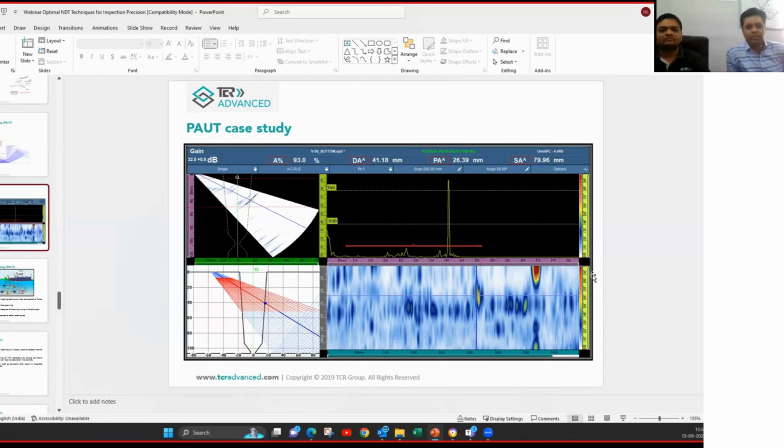Coming to your question about tank bottom plate inspection. Now there are techniques like MFL, but then you have to empty the tank and go inside and do the testing. For in-service inspection, acoustic emission testing is the right choice. It can be done with two approaches. One is that you stimulate the tank by increasing the height, that is, by increasing the overall pressure on the bottom of the plate by the same fluid which you are storing.